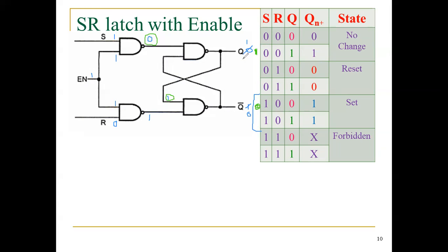So now you listen or see carefully here, whatever may be the assumption I made, my Q output is always 1. So this operation is called setting of my flip flop. In the earlier case, it is called a resetting operation.